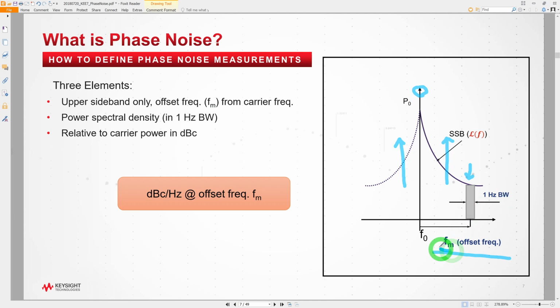So that means that this number over here compared to the amplitude over here is mentioned, and of course the carrier is mentioned. And that's what you get in this equation here. So whenever you see phase noise, you have to have the offset mentioned, the actual frequency, and of course the dBc per hertz value mentioned. That would tell people how good this source is.